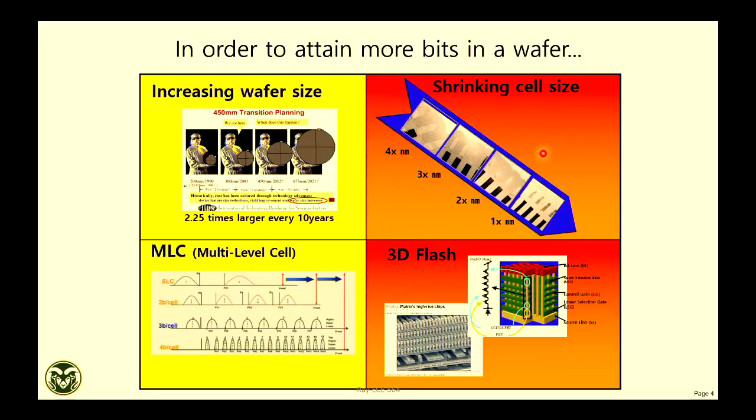It is not like you have one wafer, you have another wafer, and you put them together. No, this is not the case. You have only one wafer. You pay the price as a wafer, and on that wafer you make these multi-storied stacks of memory layers. So you're growing more and more memory layers on a given wafer, and that's how your cost is not increasing with more layers, right? You can increase your bit density, and your silicon wafer is the same, which is in the bottom. We'll talk about this technology in a little more detail in today's class.